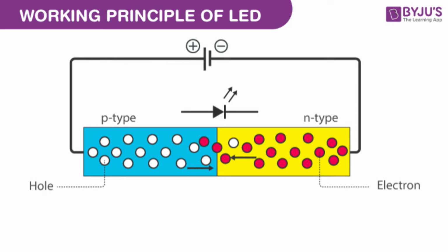But how does an LED make light? This is actually very cool. So, in simple terms, inside an LED is a union of two types of semiconductors, a positive or p-type one, which wants electrons, and a negative or n-type one, which wants to release electrons. When current is passed through this p-n junction, electrons from the n-type semiconductor are allowed to flow to the p-type semiconductor. The thing is, as this is a state of lower energy for the electrons, they release the extra energy in the form of light.